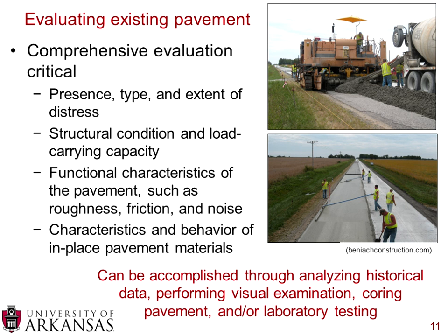And when you're thinking about what questions we need to ask ourselves when we're evaluating our existing pavement, understanding what is in place is absolutely critical. So you want to know the presence, the type, and the extent of the distresses that you have. These types of qualifications can determine whether it's a bonded or an unbonded layer.